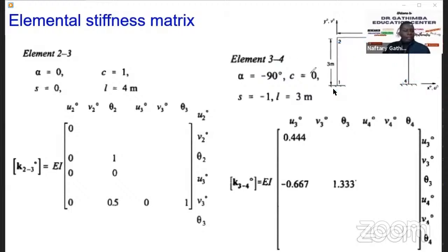And now we have the stiffness matrix for all the elements. So we just need to go ahead and assemble. And for the assembly, you can assemble the whole stiffness matrix. If you do, remember you have how many nodes? 1, 2, 3, 4. And each of the nodes has 3 degrees of freedom. So 4 times 3, 12, you shall have a 12 by 12 matrix. That's why we are playing it smart now, because we've experienced this, and we are removing the rows for the unknowns.